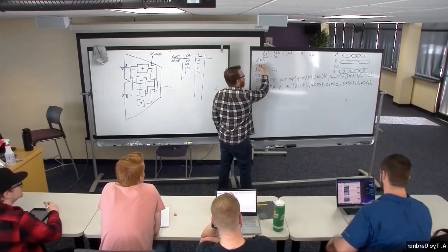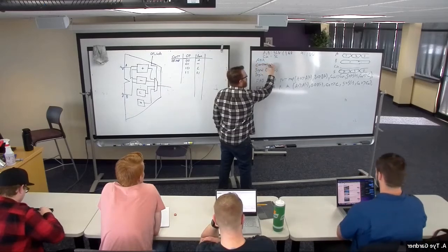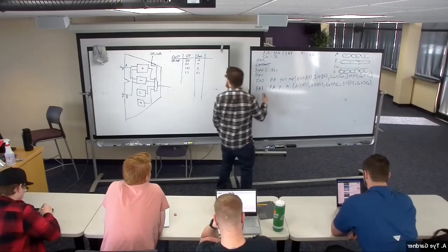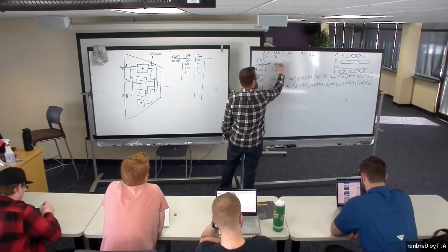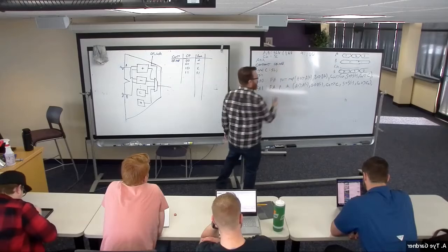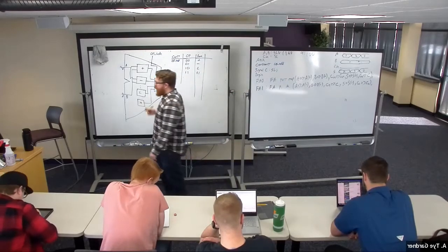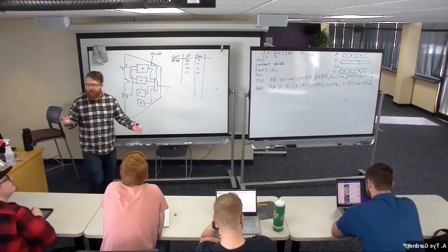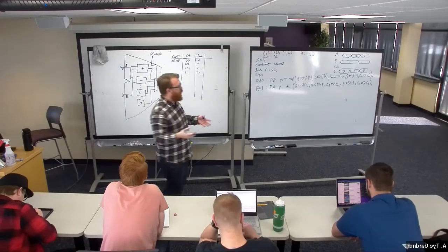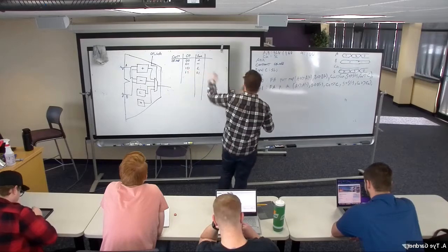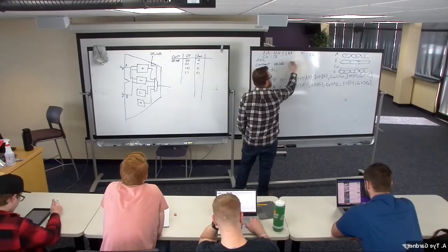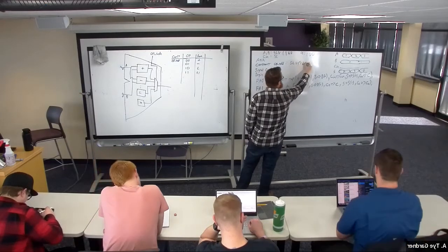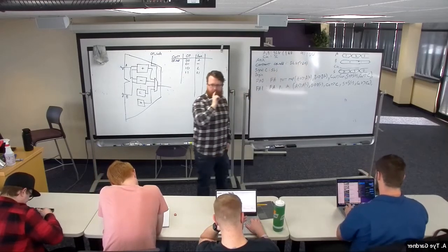I would say constant, just like signal, give it a name, op add, and then just like the signals, I need to make sure that I know what it is. What type is it? What's the data type? Op add is going to be a standard logic vector of size 1 down to 0.